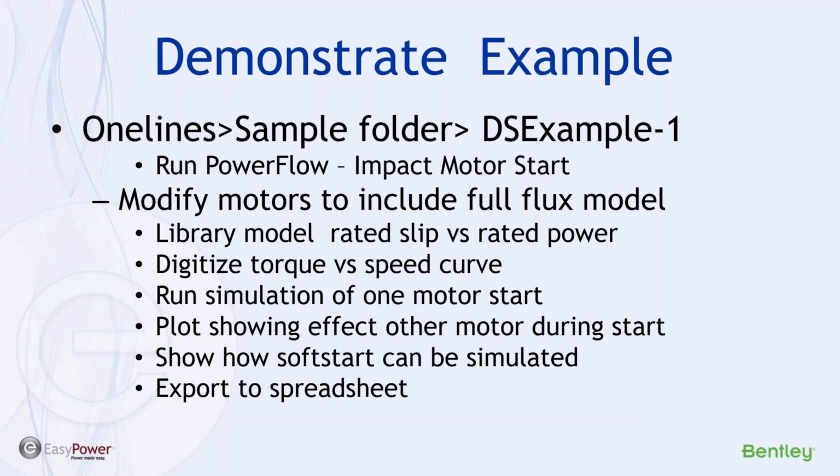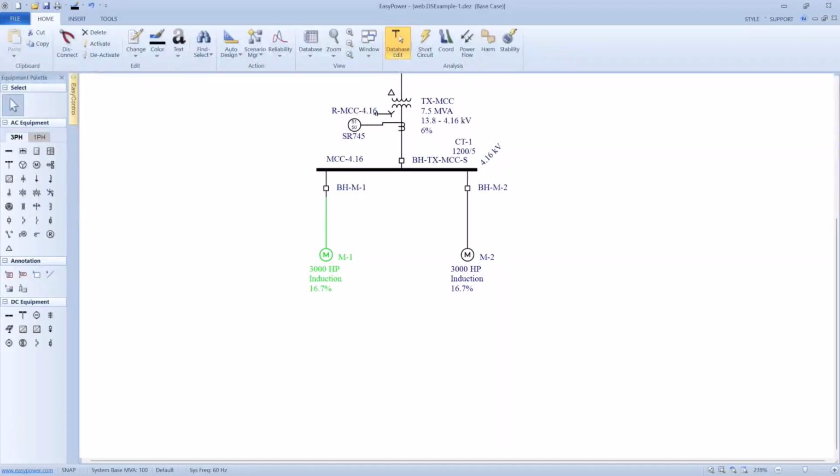So we're going to modify the motors to include the full flux model. We could do the same modeling if we digitize this torque and speed curve, show how that's done. We're going to run the simulation of one motor start and then plot the effect on other motors in the system, and then how soft start can be simulated. So we're going to try to accomplish all that in one fell swoop.